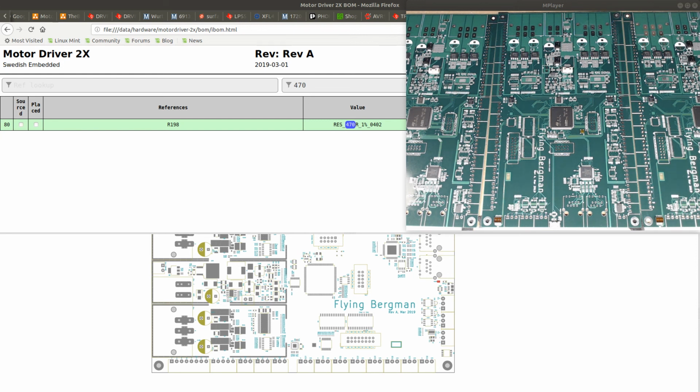And that's pretty much what this placement is all about. Just taking the components out of the bag and placing them on the solder paste. And I think overall it's a pretty boring process, but I do find some faults, such as, for example, discovering that the ground pad didn't have any solder paste, and it didn't have any mask opening. So it's useful as well. It's kind of like a second stage review of the design. Although not the final review, because the final review is actually testing that everything works. But nonetheless, I found it useful to assemble a few boards manually.